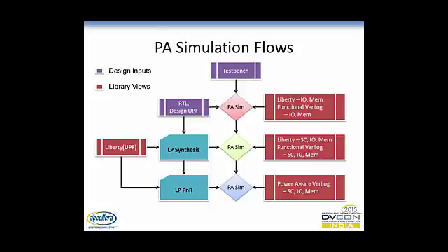Standard cells generally are not involved at the RTL stage. But for the memories and IOs, you don't have the functionality which you can model using behavioral models. So you need to use the physical IP views like Liberty and functional Verilog models for those IPs, which are directly instantiated into your RTL while doing the functional simulation. That is where you can do the power simulation at the RTL stage.